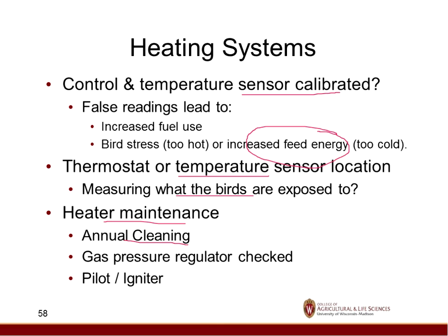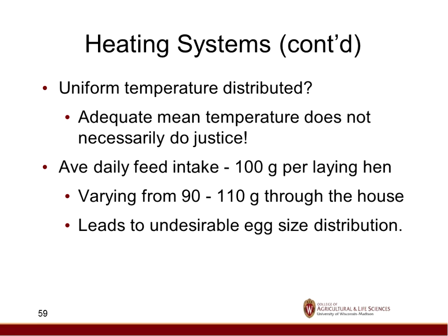And then the maintenance of the heaters. They need to be cleaned annually, possibly more often, depending on the environment. If you've got a dusty environment, you may want to clean them more often so you don't have dust build up on the heat exchangers that insulates them. Gas valves, check those. Igniters, make sure they're working properly. So that's all important.